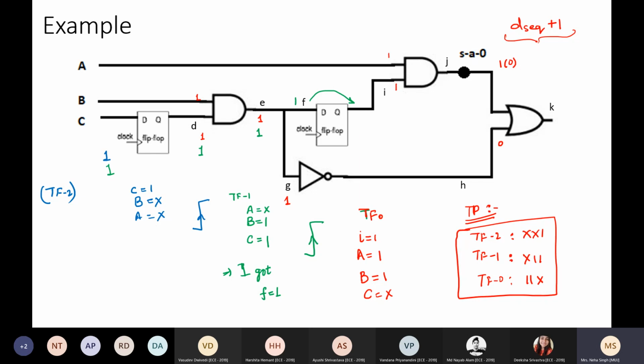We saw it for combinational circuits, we saw it for sequential circuits. Now theoretically we have said that we face this problem in sequential circuits. The number of time frames, the number of test patterns is large, right, as the number of flip flops increase. Now mathematically, how do we say how difficult it is to detect a particular fault? For that, we talked about two quantities, two measures, observability and controllability.